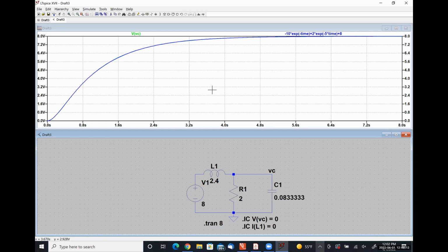If you're ever strongly feeling that your results are correct and the simulation isn't matching, again, make sure that your axes are the same on both sides of the graph. And in the event of an underdamped response problem, make sure that you have remembered to include the conversion factor of 180 over pi every time you have the term omega d.